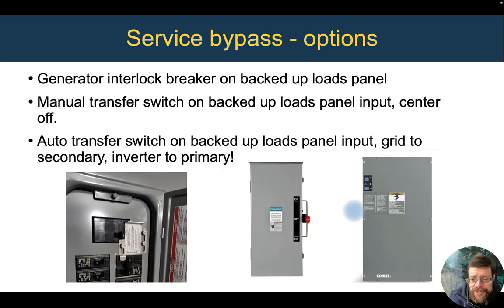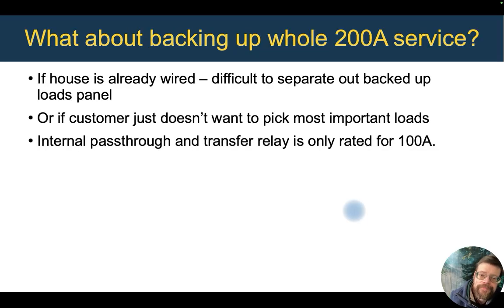So 3 different options for doing that service bypass to make sure that even if the inverter is off or down for some reason, that you still have grid power able to feed to those backed up loads.